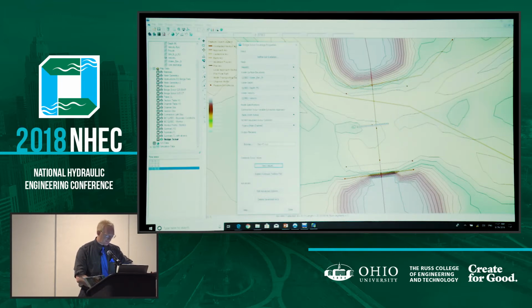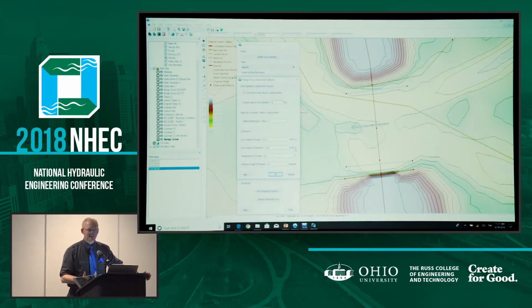So you check over that, and once it looks good, you can export it. I'm going to take a quick pit stop down here at the advanced options. This soil gradation that we entered in earlier is used to determine a critical velocity. We can come in here and say that's really more than we should have. It's really about 3 feet per second when our sediment starts to move. I'm going to override that computation and just hard code it and say, choose a 3 for me.